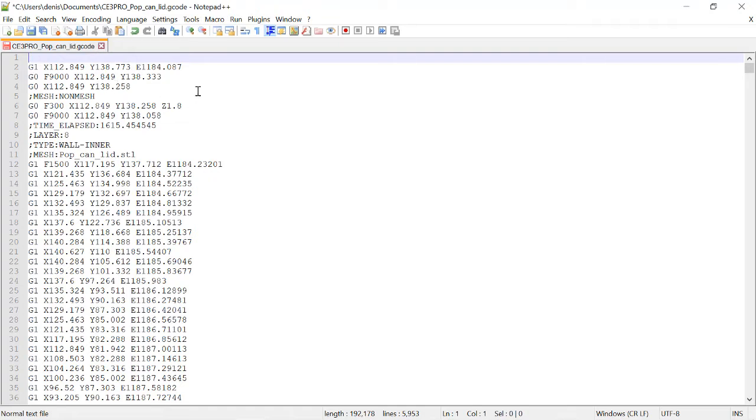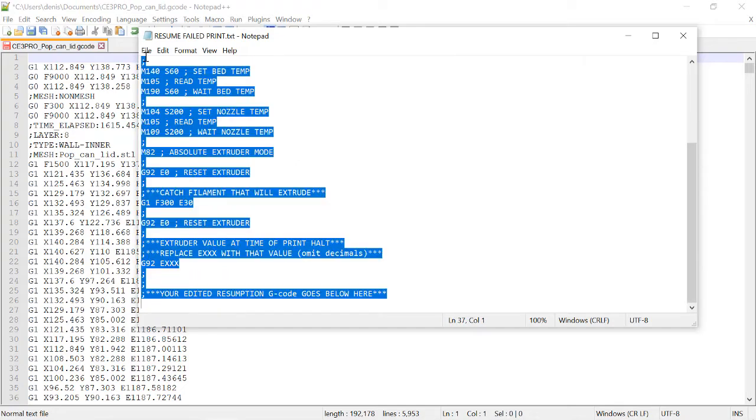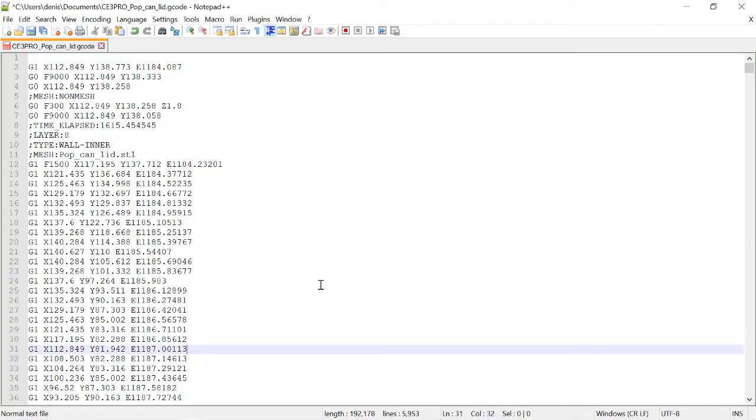And now we're at the exact location in this G code file where we were in the previous video when we did our physical measurement method. And as stated in the last video, we can't just start executing G code from this line. We need some lines of G code before it that initialize all the parameters required for the printer. So I have streamlined that process, so as not to have to reinvent the wheel each and every time, we just copy and paste this text to our G code file.